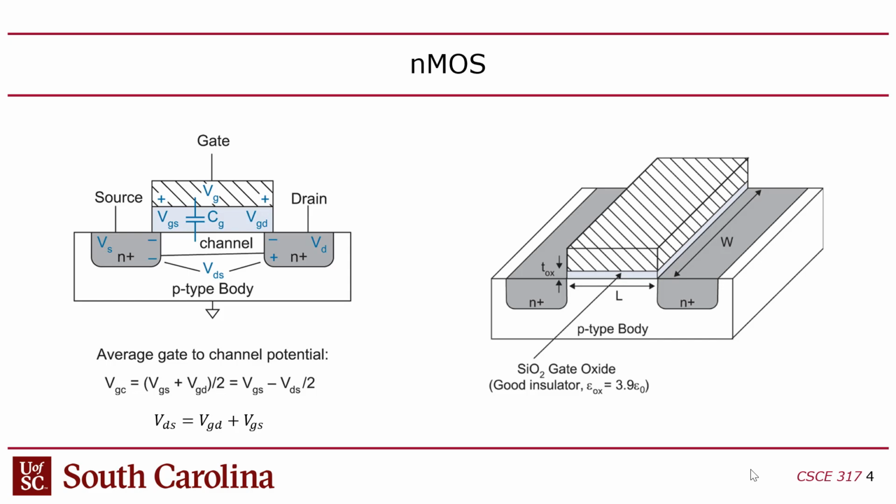So if you go from one fabrication process to another and you reduce the length by a factor of 0.3, then you're going to reduce the width by that same factor. However, you don't always want to have minimal width, because as long as the length is minimized, you might want to make some transistors wider, because wider transistors allow more current flow through here. And it allows this transistor to be stronger. It can drive more load.